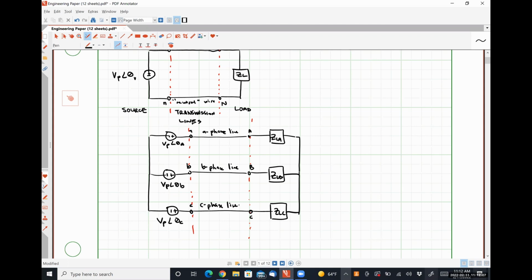And so if you consider an electric motor connected to a single-phase system, what does the instantaneous power behave like for a single-phase system? We covered this effectively a couple of weeks ago. It's got a DC portion, and then there's an AC portion superimposed on the top of it, right? So that means the amount of power that's being absorbed by the motor is constantly changing in time, which means the amount of torque that's being provided by the motor is constantly changing in time, which means the motor vibrates,